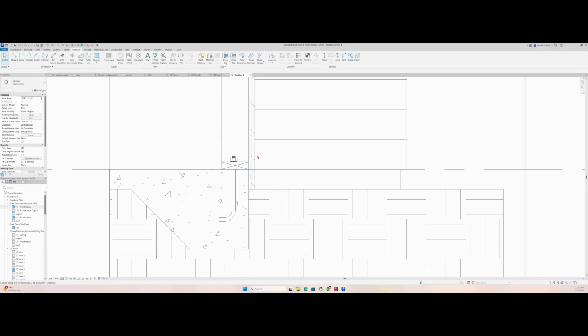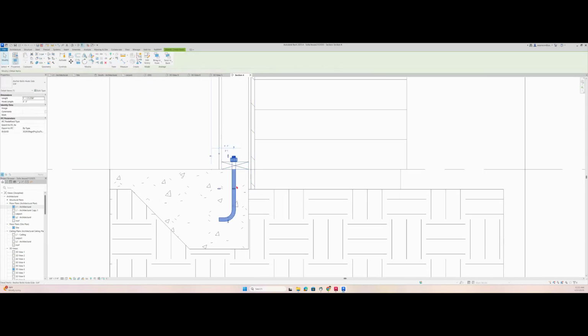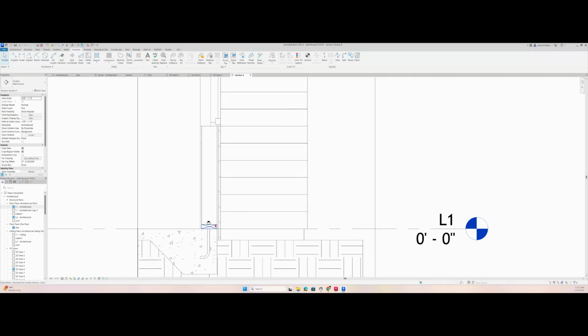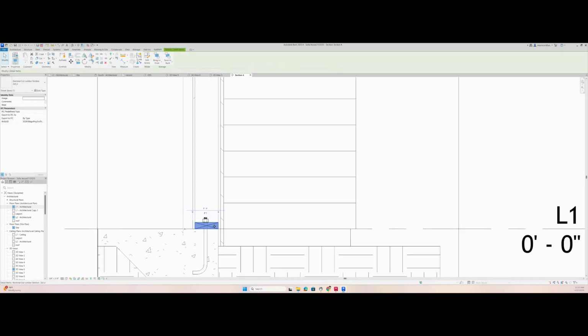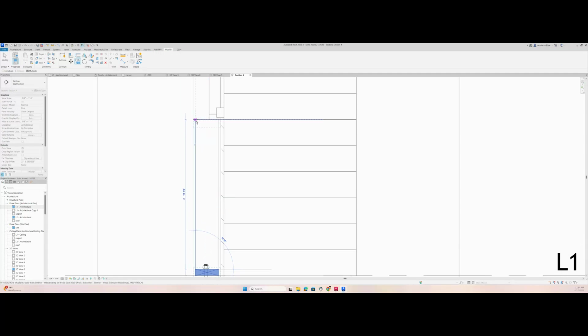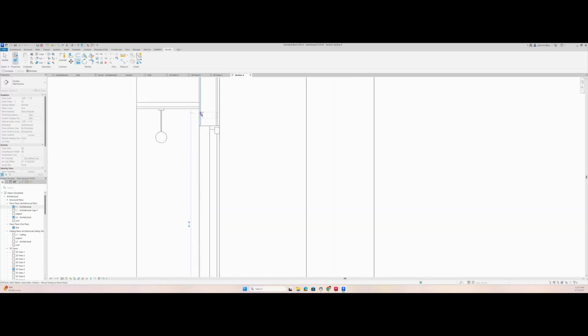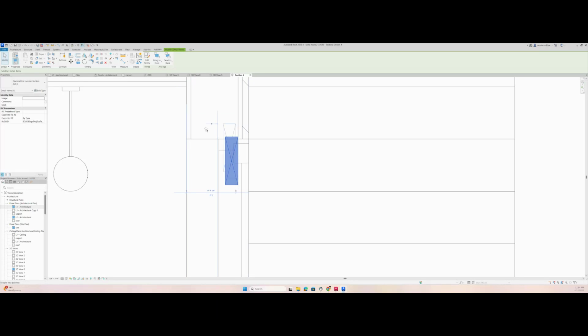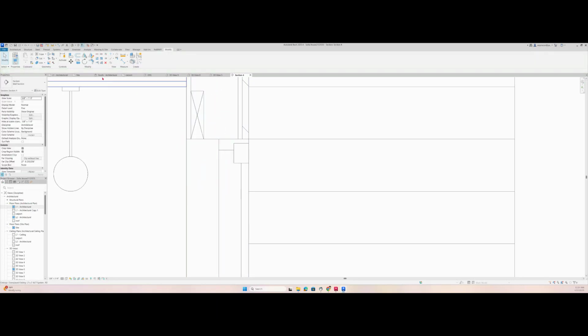The order of the detailing, because I brought first this one, is like behind the wood blocking, right? Something else to do, now that you brought in and customized this guy, you can copy it so you can do your wood framing here, right? So here and here. And on the top, let's put him here, but this one goes the opposite way, right? This one goes this way, and we place one here.